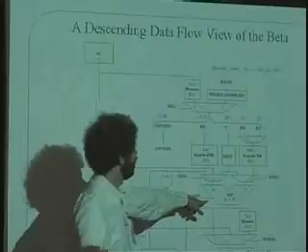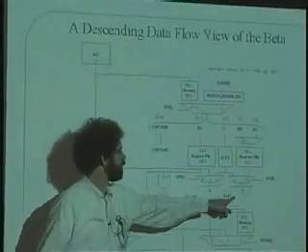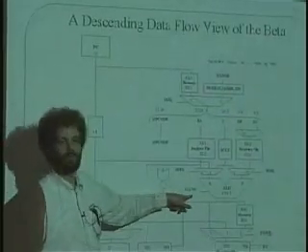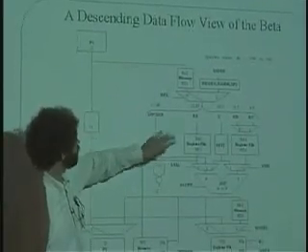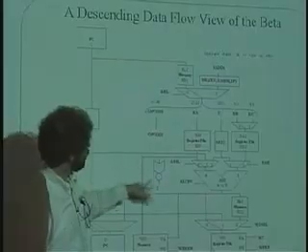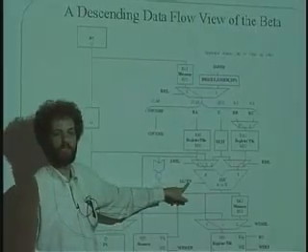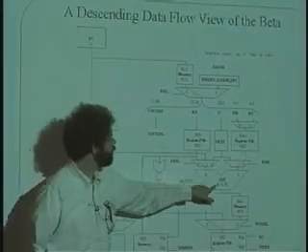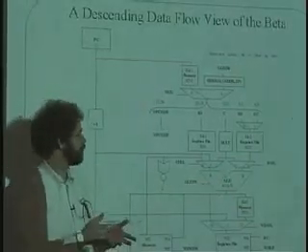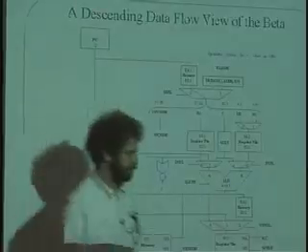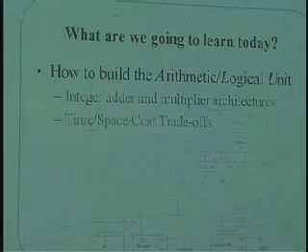We're talking about this thing right over here. It takes the A and the B and takes some sort of an opcode from the instruction stream that is decoded. In other words, there's going to be some logic between this opcode and the command to the ALU saying what function to do, and the ALU is actually going to do the work, and it's going to do things like adding and subtracting, and, or, XOR, stuff like that.